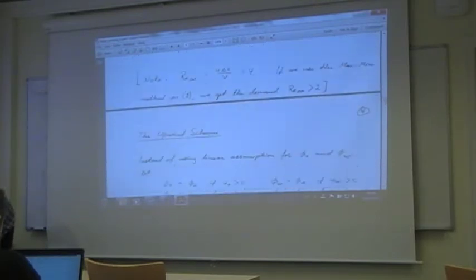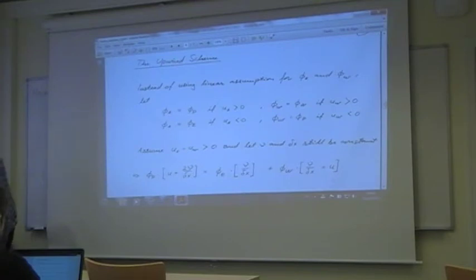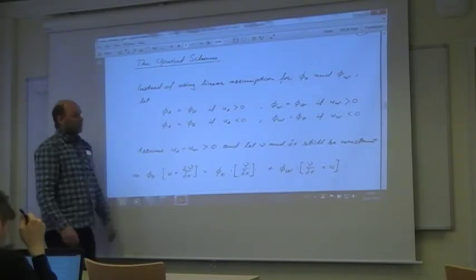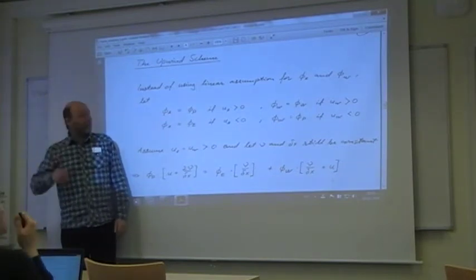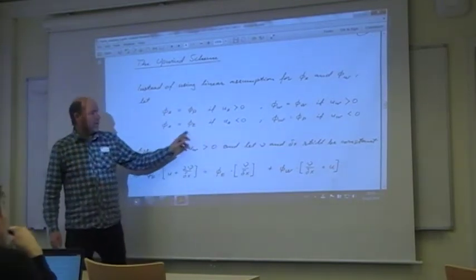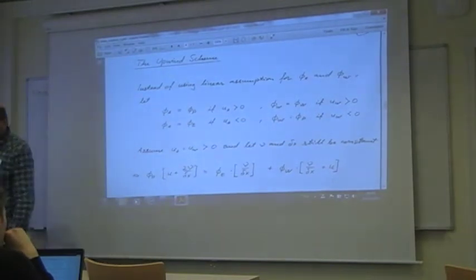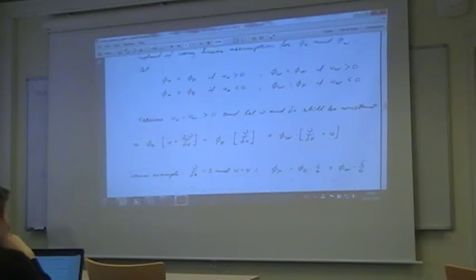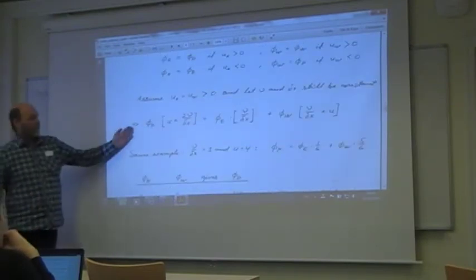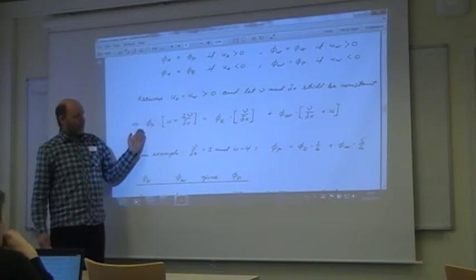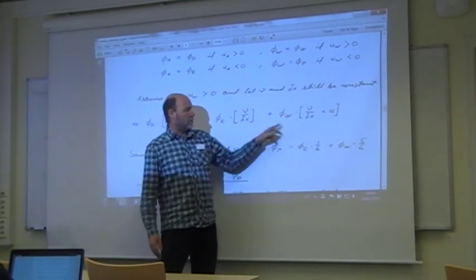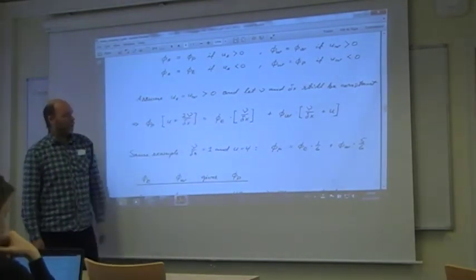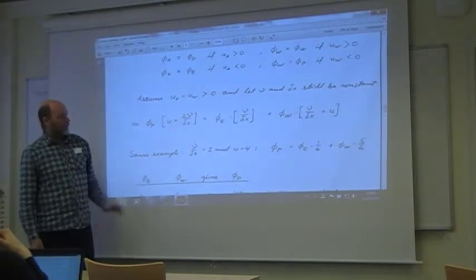Now Patankar continues with the remedy of first order upwind. So if the small u is positive, then yes, you just choose the upwind point to the left. If it goes negative, okay, then you choose the other one to the right. And the scheme you get now looks something like this. And again, yes, the sum of the coefficients is 1. You add these two together, you have 2 times the viscous term plus u, which is exactly what we are going to divide with anyway, so the sum is 1.